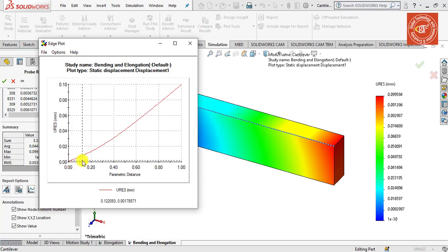the displacement plot along an upper edge in x direction, and the resultant displacement changes non-linearly, as in this case the pressure force is acting at this side, and you can find the maximum displacement at its free end is 0.09958, maybe a slight deviation in the result at your end.